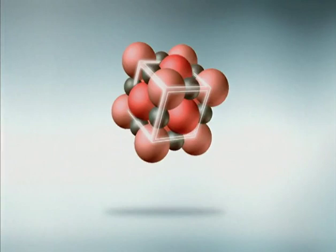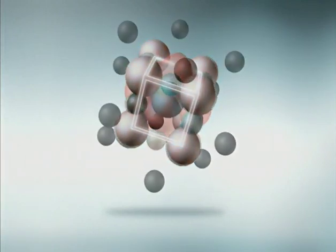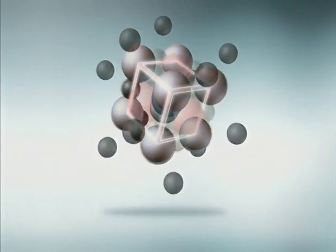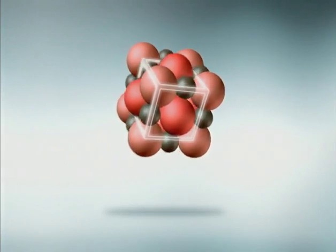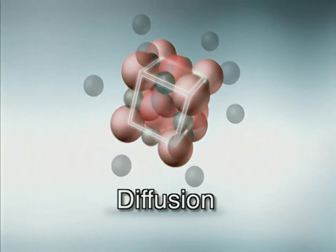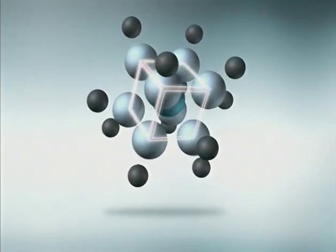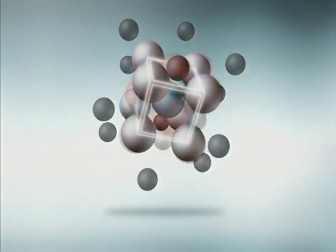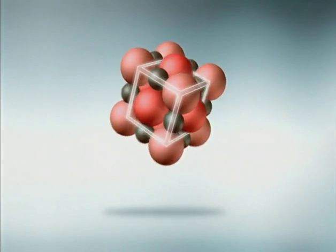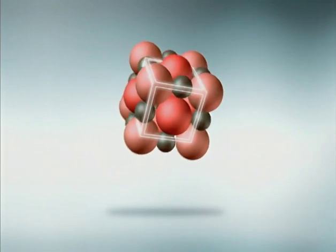The FCC lattice of austenite has more space available for carbon than the BCC microstructures that form below the transformation temperature. That means that the phase changes that occur during heating and cooling require the diffusion or movement of carbon, and diffusion takes time. So let's see what happens to carbon steel when there's enough time for diffusion to occur. To simplify matters, we'll limit our discussion to steel with less than 0.8% carbon by weight, since you'll seldom have to weld on metal with higher carbon content than this.